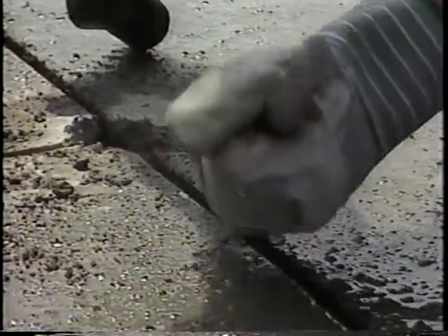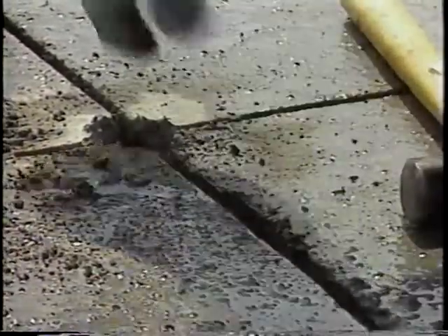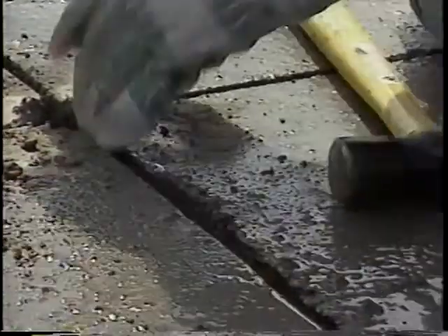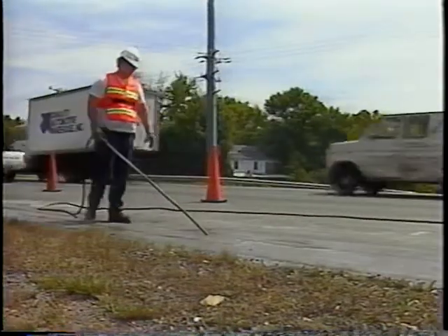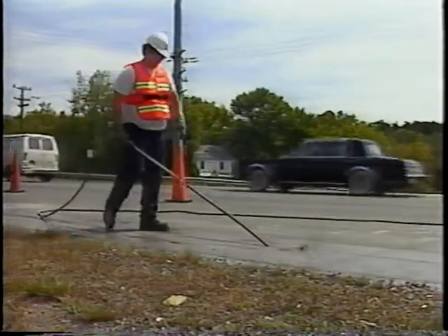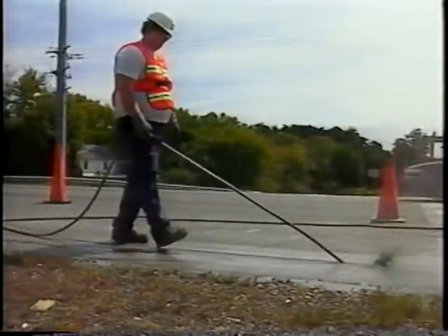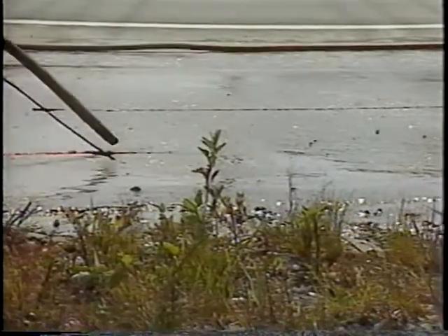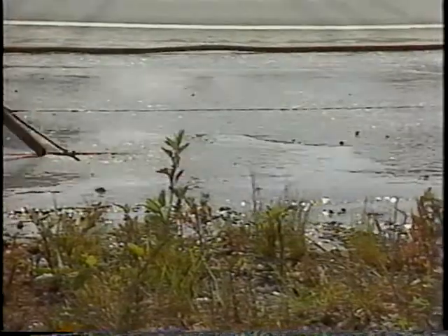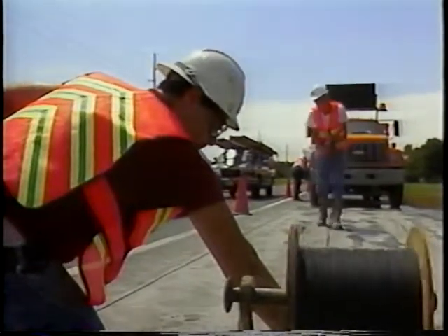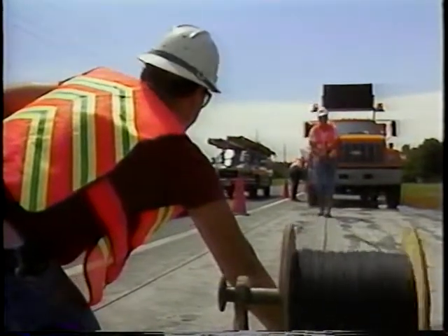Finishing the saw cut is an important installation step. Cleaning the saw cut, including removing all jagged edges with a chisel and hammer, should be done immediately after cutting. It is crucial that the saw cut is clean, dry, and free of dust, grit, oil, and contaminants. The recommended practice is to flush the slot clean with pressurized water, then dry it with compressed air. Take care not to blow any debris in the direction of passing pedestrians or vehicles. After the slot is saw cut and cleaned, it is ready for the loop wire.